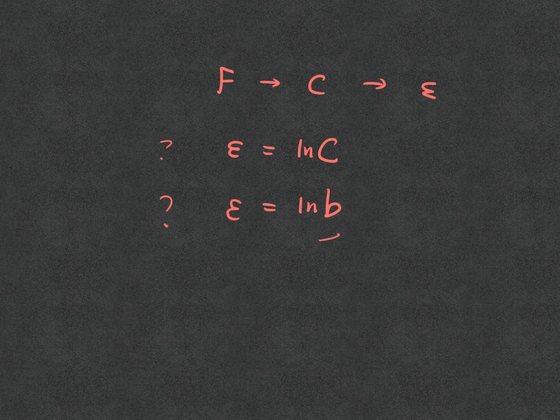So which one is correct? Obviously, only one of them is correct. It depends on how you view what the deformation gradient is performing. So without further delay, let me talk a little bit about this. In this case, we will use the textbook idea, where we focus on the development of the constitutive law based on the left Cauchy-Green tensor. But keep in mind that it restricts us to isotropic material.